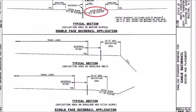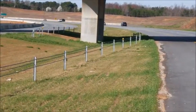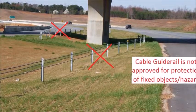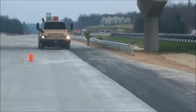Please note that this is not an acceptable installation practice. Cable guide rail cannot be used to protect median hazards like this median bridge bent. Strong post W-beam guardrail must be installed to protect these hazards.